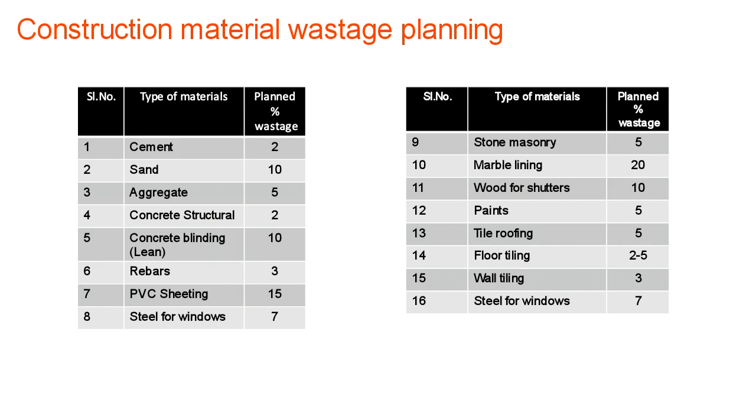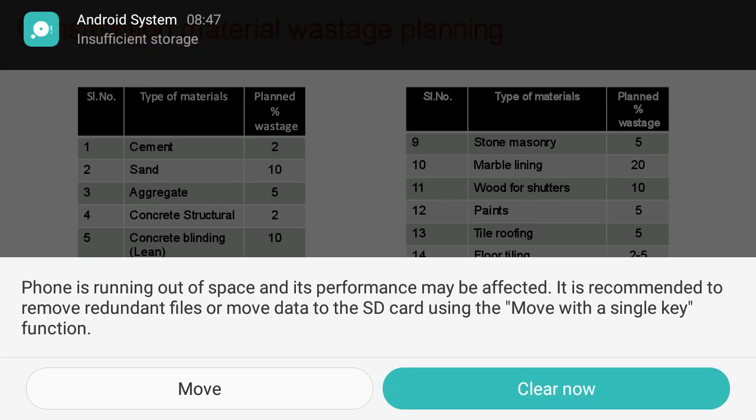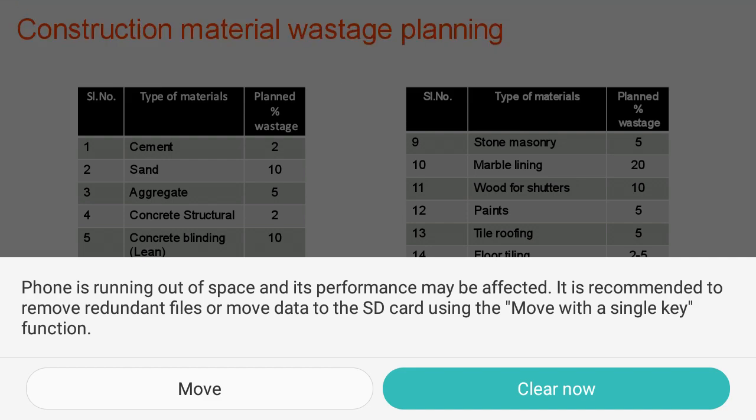because this rebar wastage itself has some three classifications: one is visible, reusable wastage, then another is scrap or non-reusable wastage, and another is invisible wastage. There are some relatively large pieces of rebar which can be reused in other places, that is the reusable kind of wastage. And there is another category of small pieces which cannot be reused anywhere, and that will go as waste or scrap, so that is non-reusable waste. And another category is completely invisible, because that will be small cuttings and all, which you will not be able to identify also.